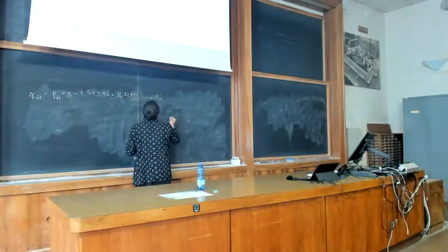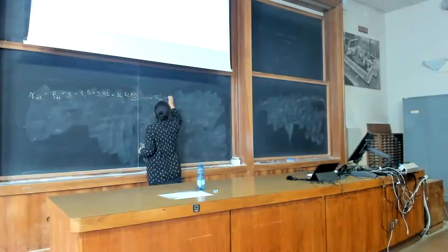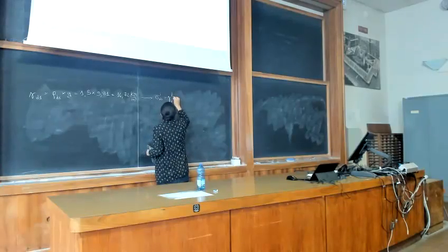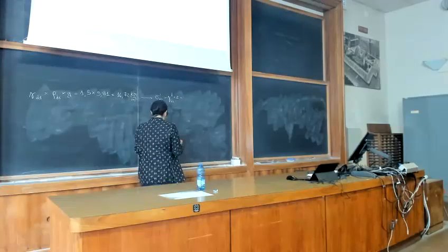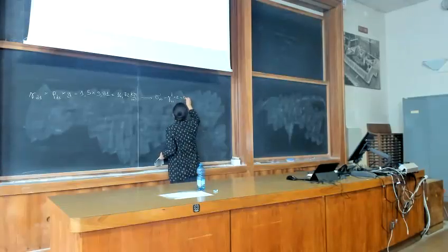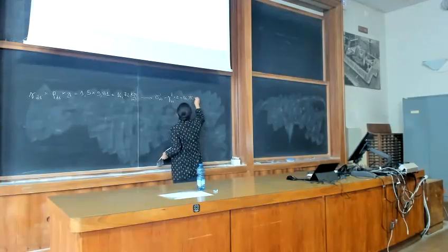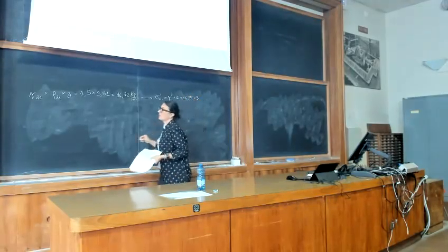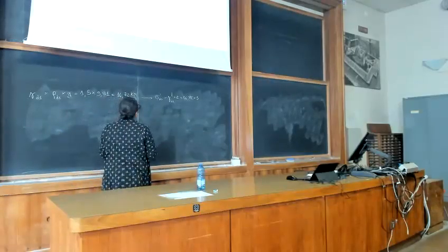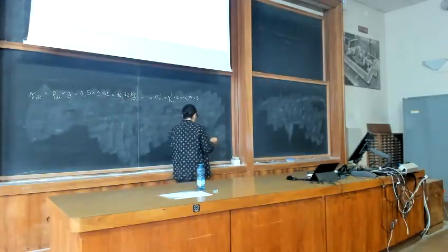So you have sigma dash v0, which is gamma dry of the first layer, 14.72, which multiplies 3 meters, which is the depth. Yes, 3 meters is the depth of the first layer.